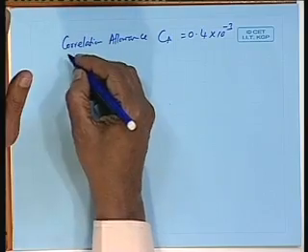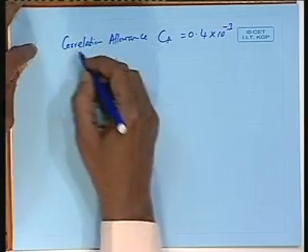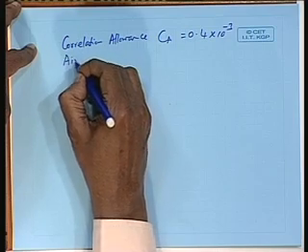So, roughness allowance will be somewhat dependent on length. So, now ITTC has given a formulation for correlation allowance which is dependent on length, that is given in the 1978 ITTC resolution.